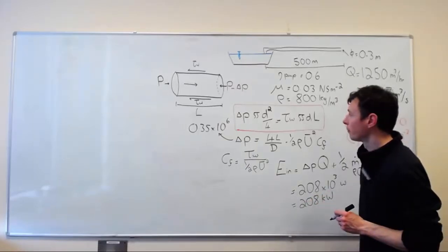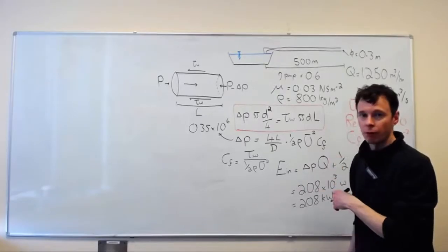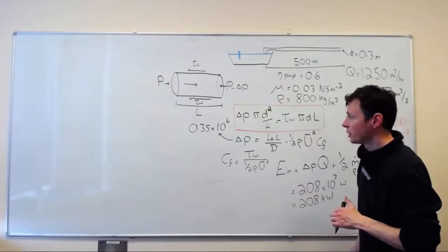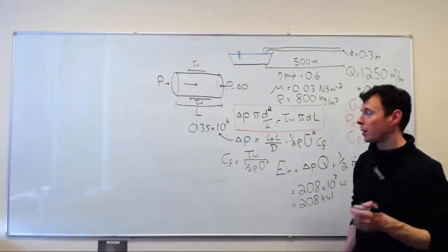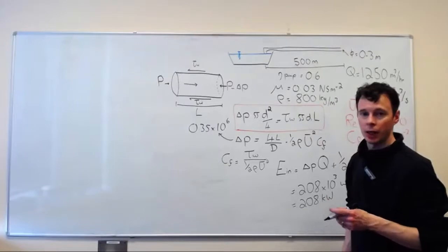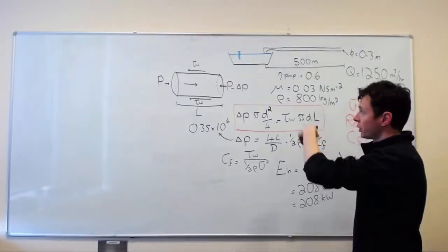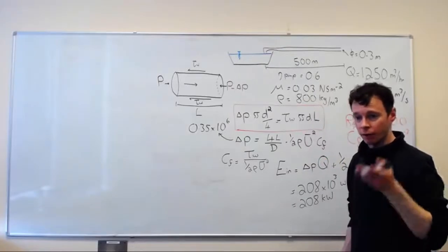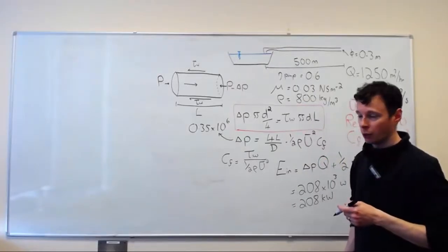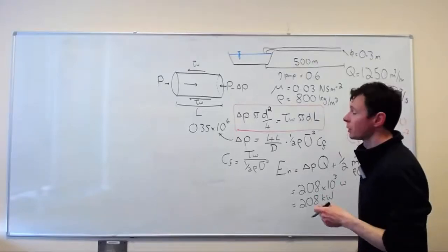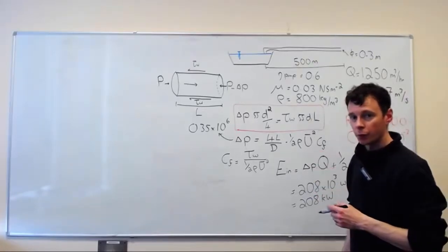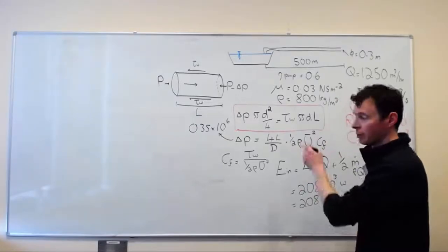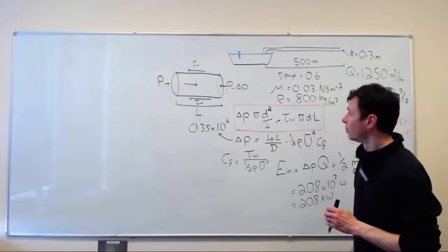Okay, I'm quickly going to rub this lot off and then we'll tackle the second part, which isn't too onerous. If you read the question, it says that now the pipe diameter has changed and we have a vertical element, so we have to take into account the mechanical energy to lift, so the potential energy to lift the oil up, so rho g h. So we have to add that in as well towards the end of that part. So I'll fade to black quickly, rub this off, and we'll do part 2.